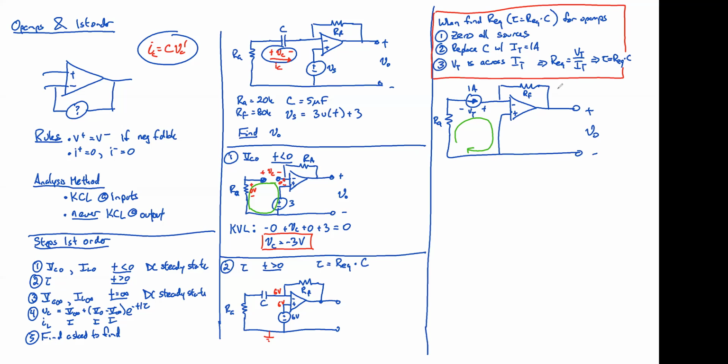When I go through it, I could go to the right, but that looks more complicated. This looks really simple because I know some of these voltages already. What's this voltage going to be? 0. I drew a different sign convention, but it doesn't matter. It's 0. I just don't know what this voltage is. If I could figure it out, the whole problem would break apart, because I could do my KVL: this voltage, plus this, minus this unknown voltage, plus 0 equals 0, and it'd be set.